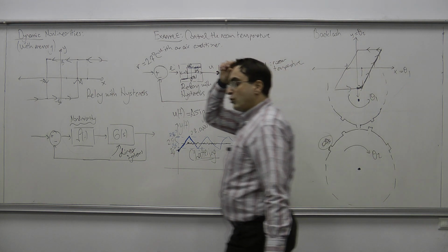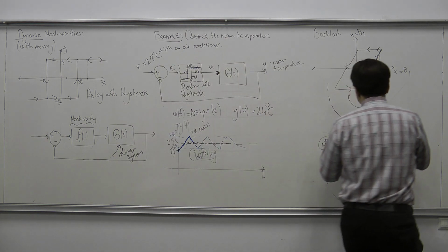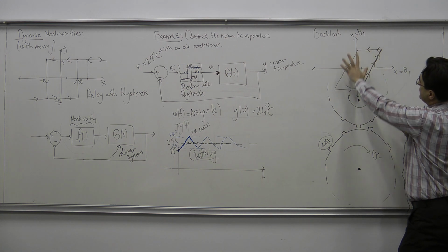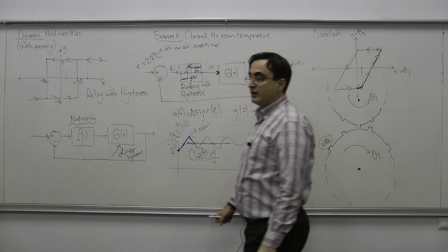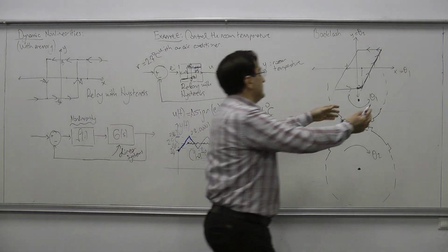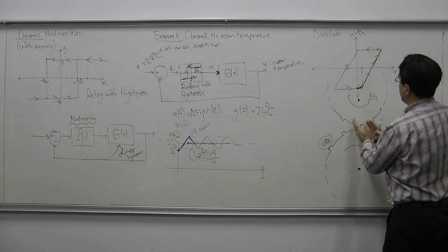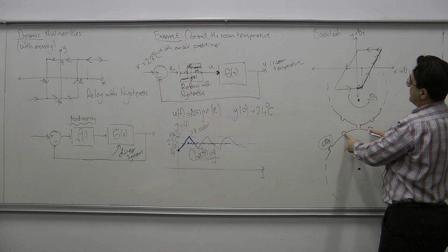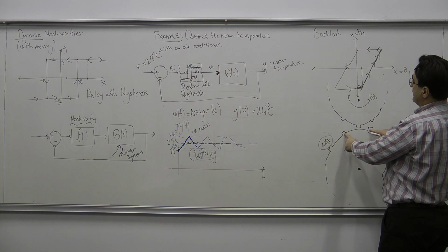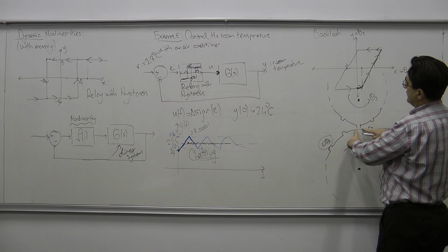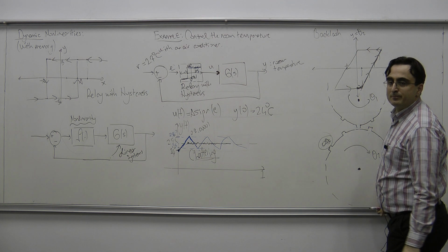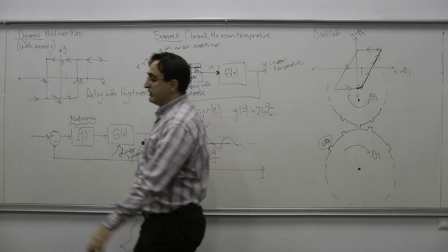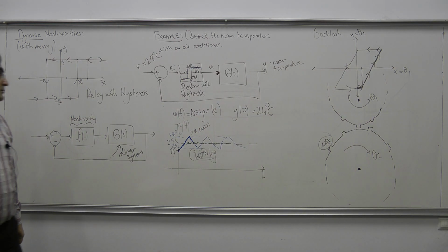Okay? So it is this type of space between the cogs of the gears that would cause a backlash type of nonlinear behavior. Of course, usually this behavior is constrained to very small angles, okay? Because we don't really have gear cogs separated like this in reality. They are separated, but with a very small distance between them. All right? So that is still a behavior that might cause oscillations in nonlinear systems, okay?